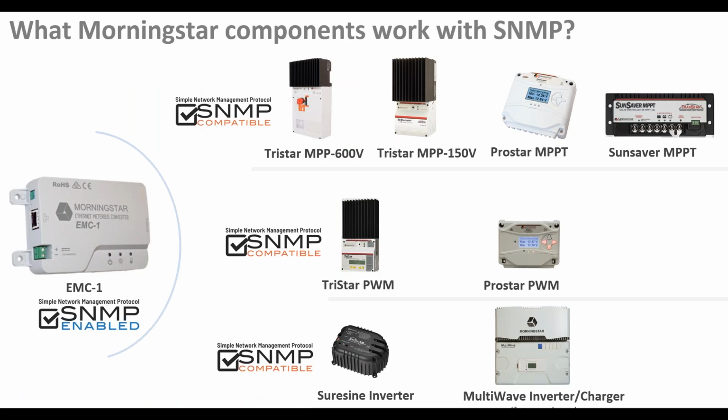All right, so going forward here, let's talk a little bit more about Morningstar and how this all is integrated. This is a list of all the specific components that are supported, all of our MPPT controllers, the PWM controllers, TriStar PWM, ProStar PWM, are data enabled and supported by the EMC1. Therefore, they can all be retrofitted with SNMP capability. All that they need to do is a simple firmware update on the EMC1. You don't have to update the firmware of the controller itself, just the EMC1. I'll tell you how to do that in just a sec.